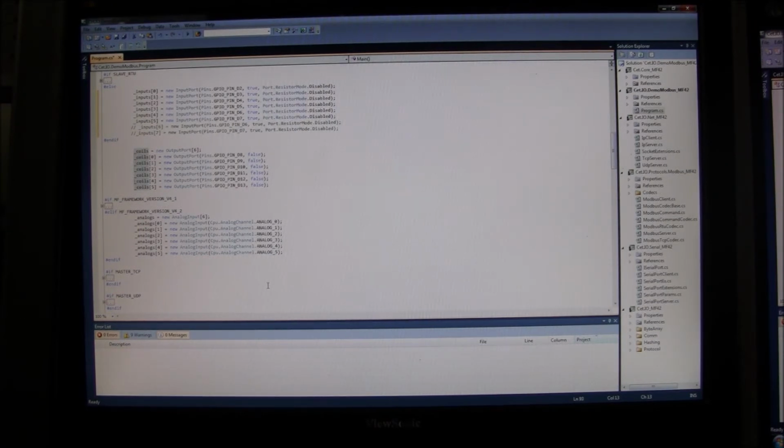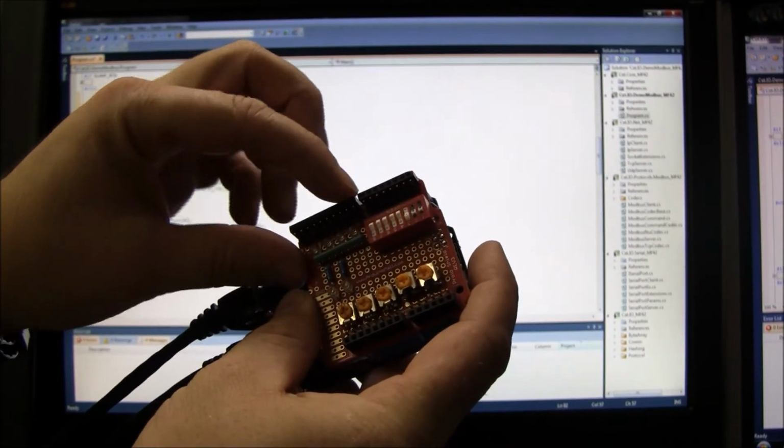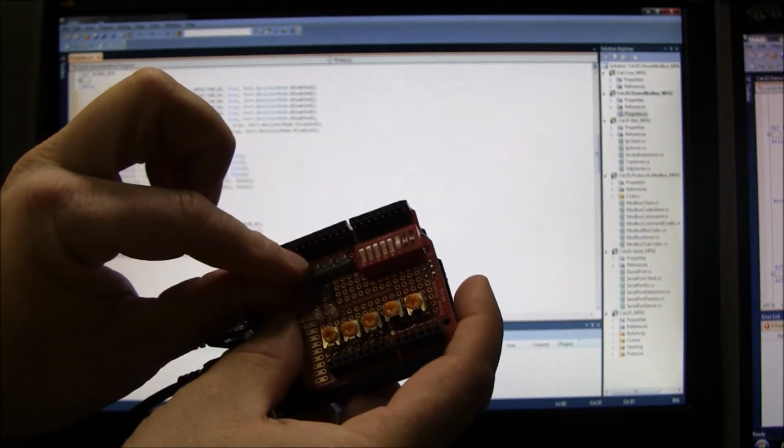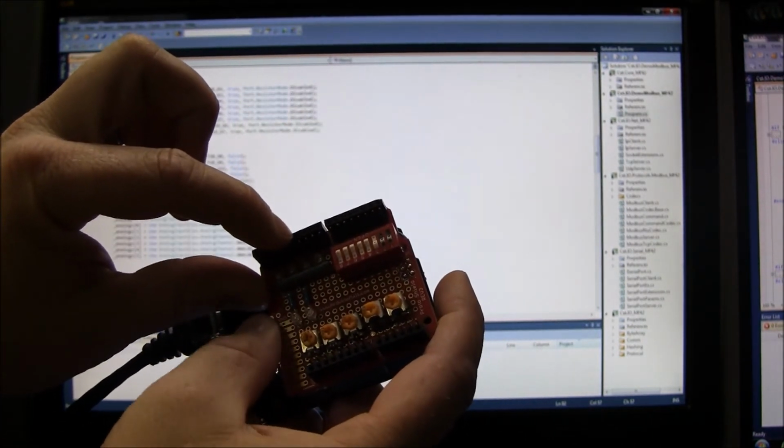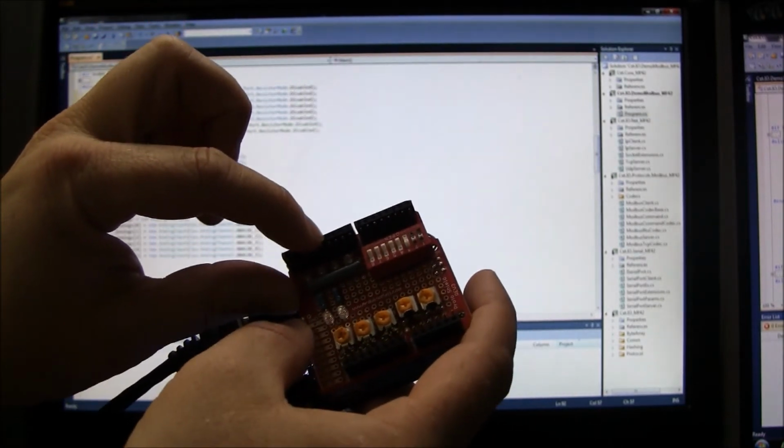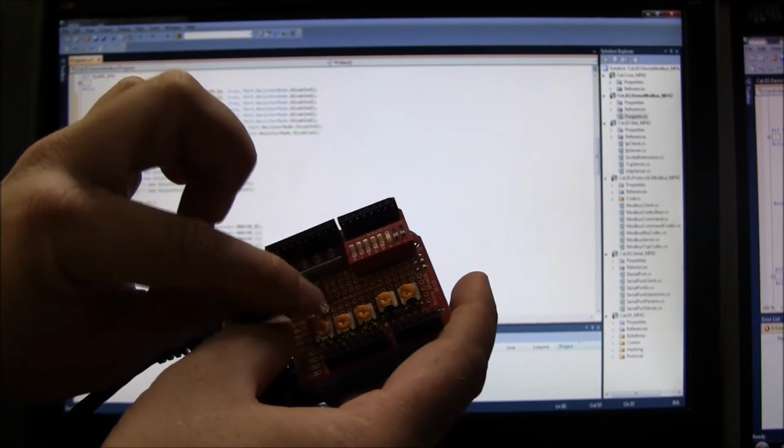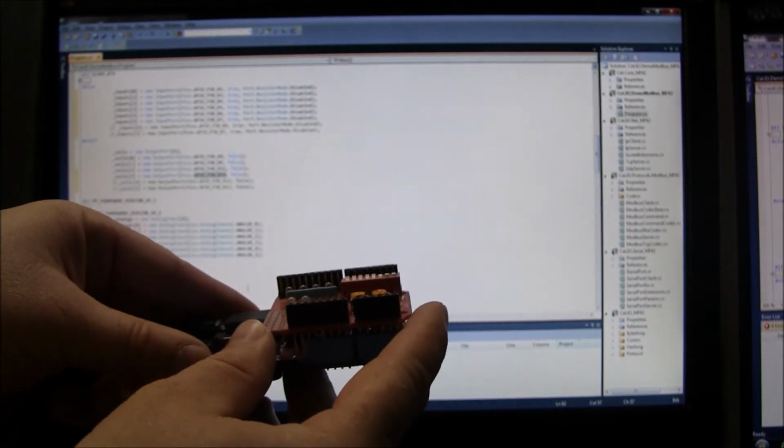And then the coils, I only have 4 of them. And when I ask for 0, I actually want to do 8 and 9, which is good. And then I want 12, 13. The reason I do that is I'm usually using 8, 9, 12, and 13 for these. 10 and 11 can be pulse width modulation outputs on an Arduino, so these are actually analog outputs. Just specific to my application here. And then we've got our 6 inputs there.